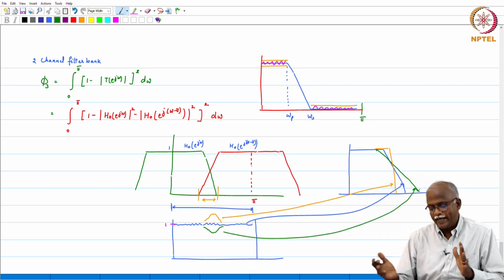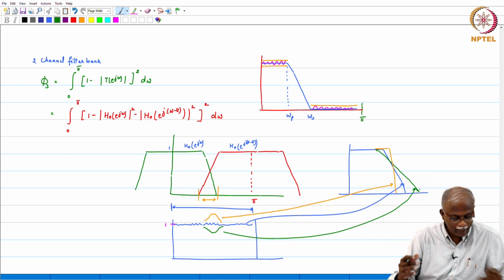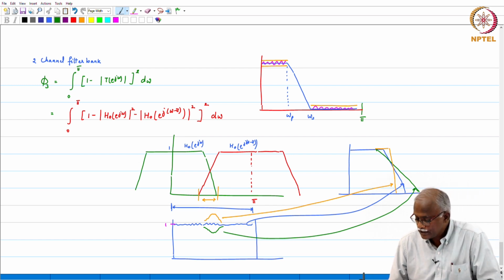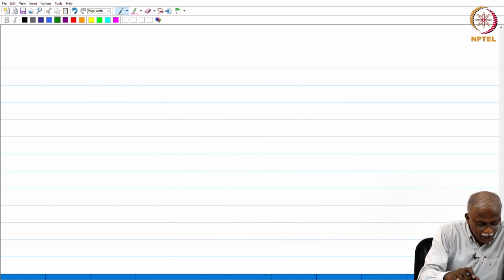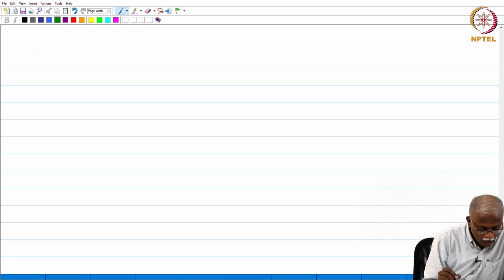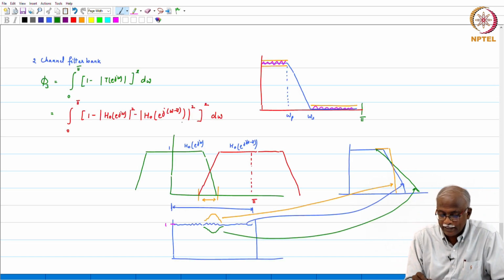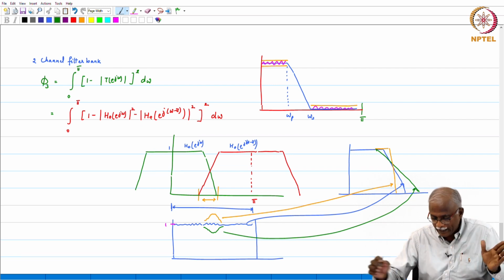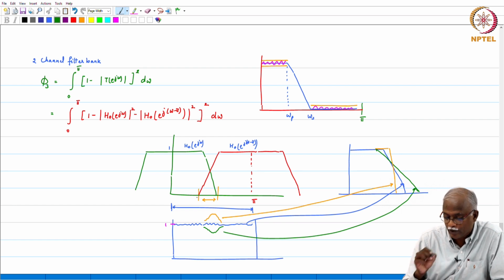Now yes, we don't know ahead of time how to design the passband and the stopband, but this is what we will do via the optimization method. So here is the optimization step, or the step that we have to do the computation. Notice that we have to apply the following condition. We want to have a very good flatness constraint over the entire frequency band, and that will be to a large extent satisfied if you have a good stopband condition, because if there are large ripples in the stopband, you will notice that the flatness constraint will also get affected.